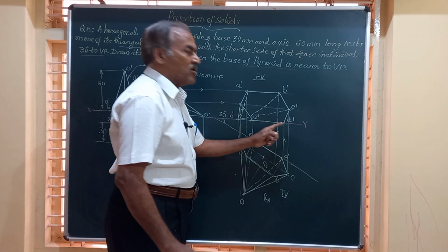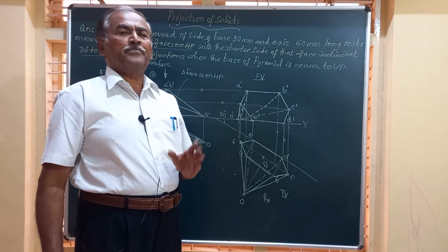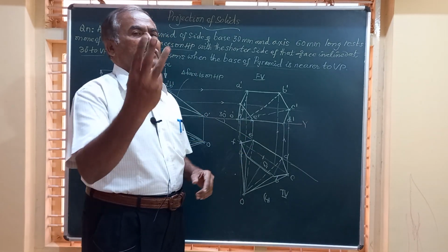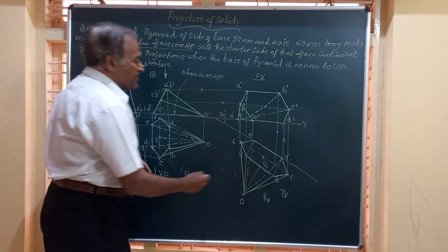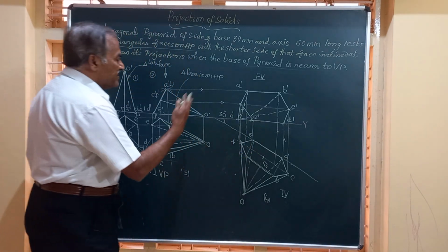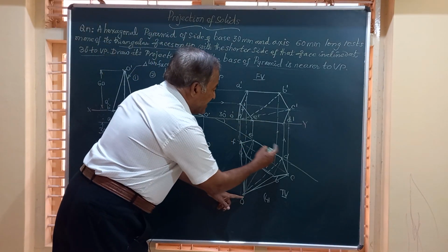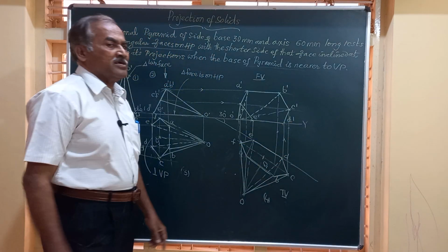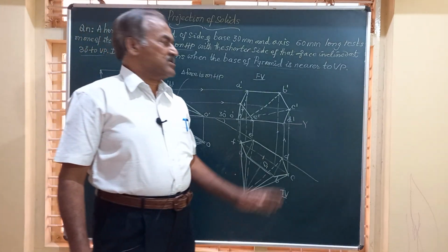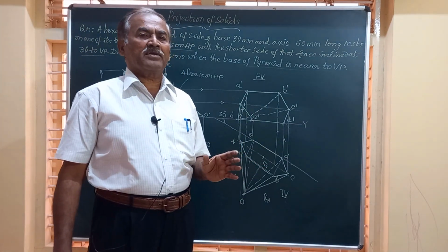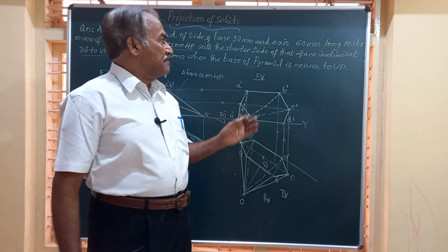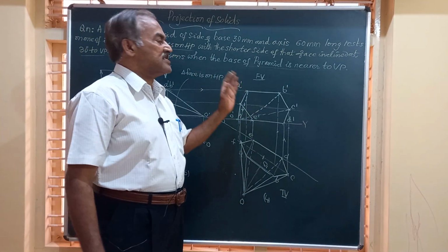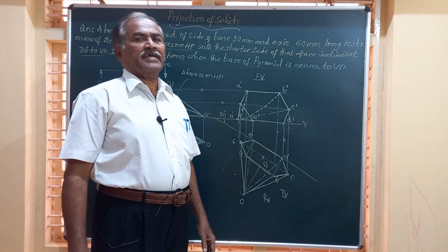So this horizontal line on xy represents a triangular face which is on HP, because that line has got only 3 points. Next, the shorter edge of that face, OED, the triangle, shorter edge is ED, that ED is on HP. Hence friends, this solution is satisfying all the parameters that are required as per the question, and hence this solution is completely correct.